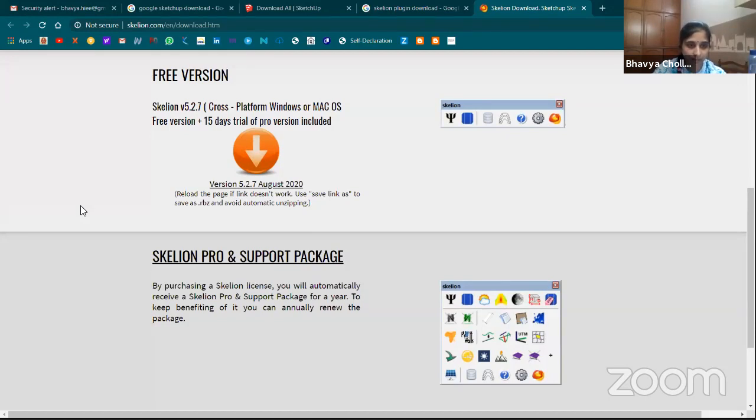I'm clear, ma'am, that at the edge of the building we can't place solar modules, but there exist some modules at the edge. You can erase them. Sometimes what happens is, if you can't form a string properly, it gives you only modules in that aspect. You don't need to worry about it. Now if you want a proper layout, you work on it. A string is a series combination of modules, guys. The series combination of modules is called a string.